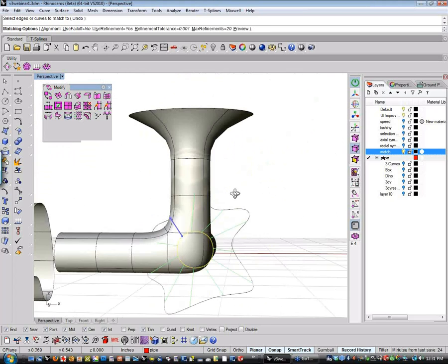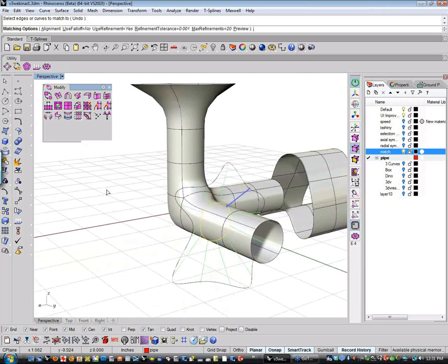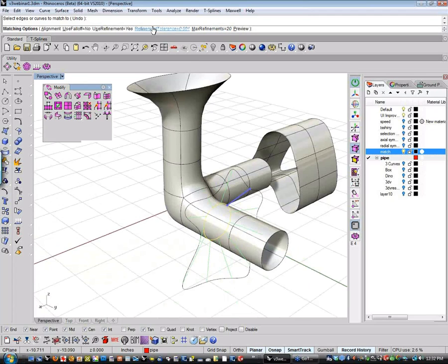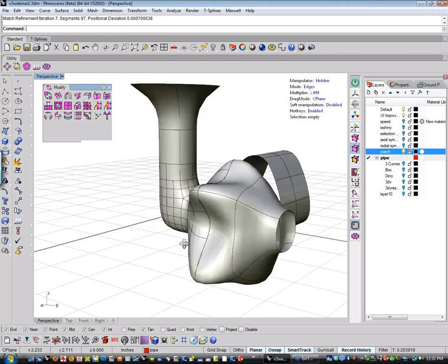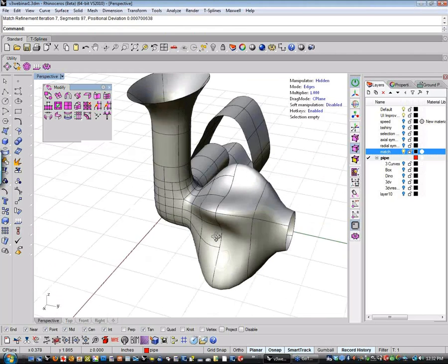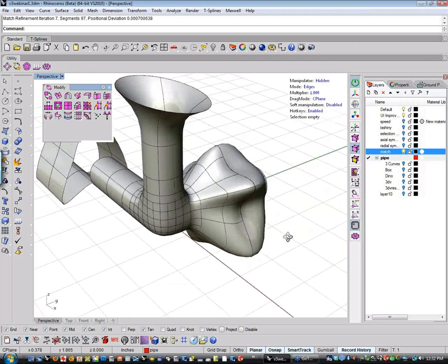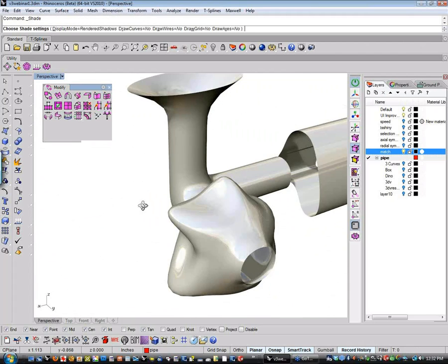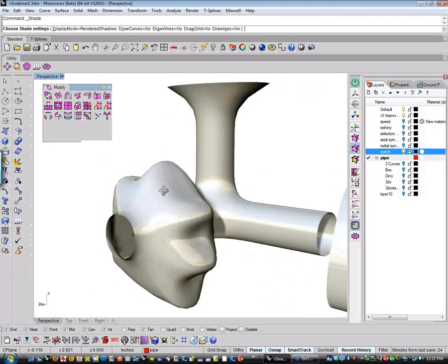I'm going to check my alignment, and in this case the alignment looks really good, nice and straight, no twisting. I'm going to go ahead and use refinement again. I'm going to let it refine 20 times and to go within a 0.001 tolerance. Right click to accept. Notice up here that it's iterating, and it found within 7 iterations and some subdivision added into the surface that it has kind of blow molded that pipe to match that curve within tolerance. And if we shut off the ISO curves, you can see that it did a really spectacular job of doing that.